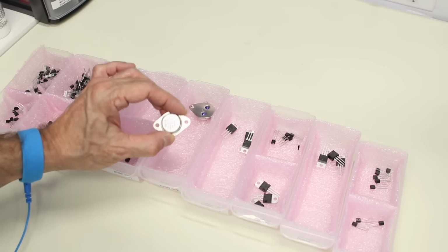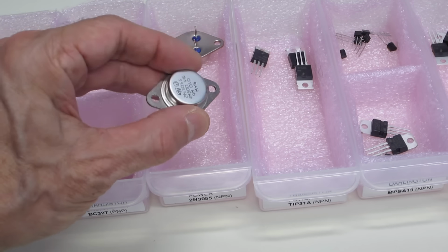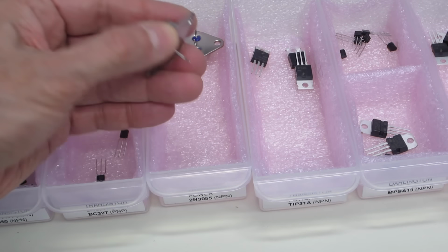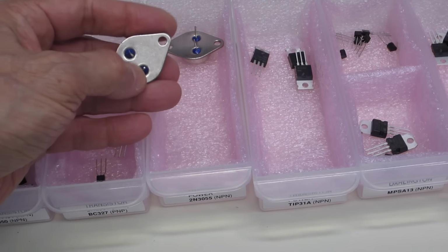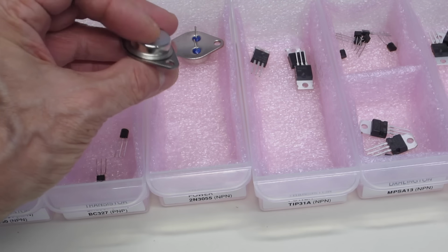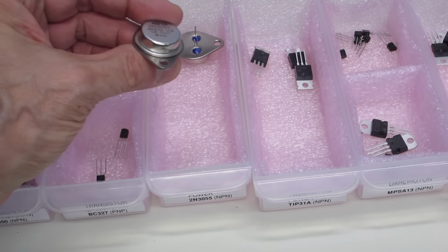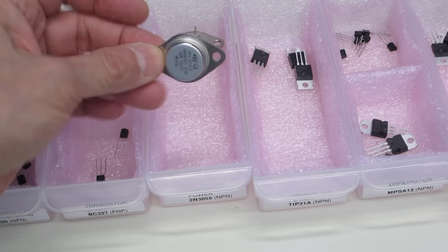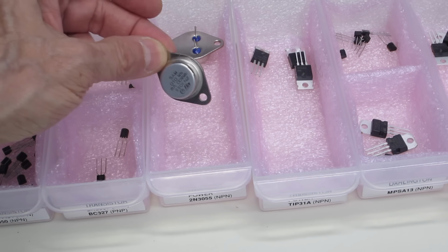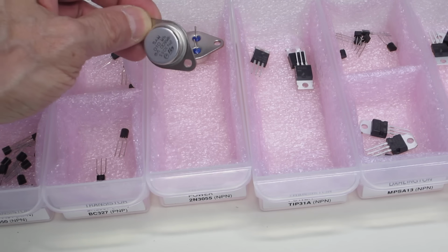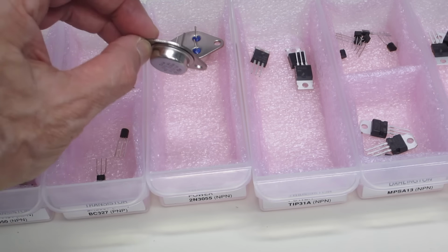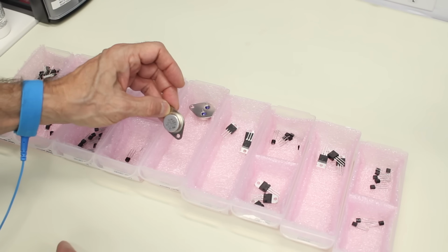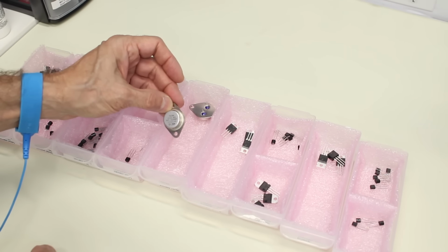This big package over here, I believe they call a TO66 or a TO3. I think it has two different names. In this kind of package, you'll only see two leads, and you'll see that the case is connected, I believe, usually to the collector of the transistor. That's one thing to note: these are obviously power transistors from the size they are. When you bolt something like this down to a heat sink, which you're going to want to do to get the maximum performance, you have to remember that one side is actually connected to one of the leads. In fact, that's how you connect to it. So if your heat sink is grounded, you could end up shorting something out depending on your circuit design.